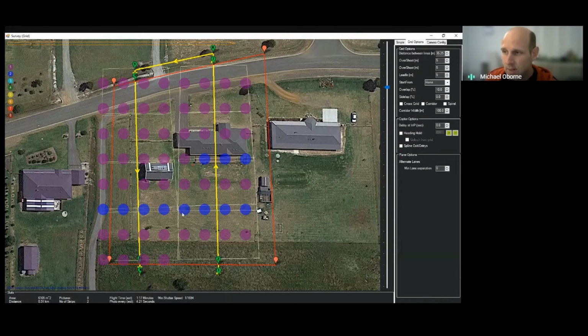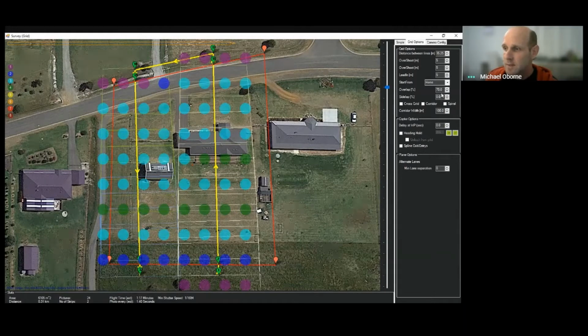Just from looking at this, I can tell down here at the bottom is 36 meters, and towards the top it must get higher, close to where the 42 meters is, because we're getting closer to the ground. The amount of ground the camera lens sees is actually less. This is the reason for using 70% overlap. So with 70% overlap, you can see now that we're getting a lot better coverage.